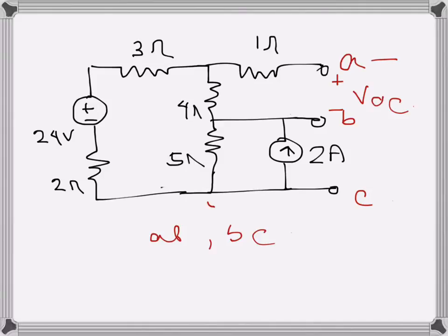So we have a current source and a parallel resistance here, and this is the terminal here. So we can actually do the conversion. We can convert it into a voltage source and a series resistance, because these two terminals are just one terminal basically, this is not affected. So we can do that. I will go to the next page and do the conversion there.